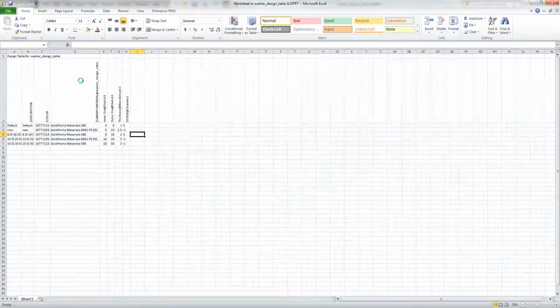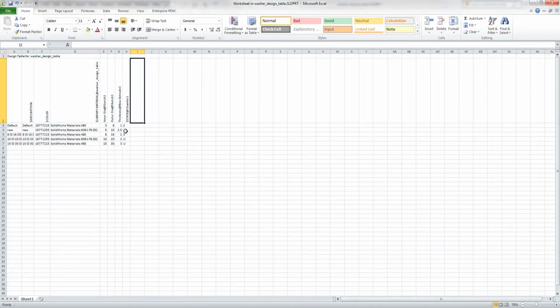One last thing I want to show you guys here, and I mentioned the drop-down lists, and you guys might have saw that pop up here. So this is the drop-down list. We can see when I click on here, it's telling me all the possible options that we can use. We can type in suppress, we can type in unsuppressed, we can use an S, U, 1, or a 0. That's going to be all the results. And then this is the actual drop-down list here where we can select those options. So each of these can possibly have an option. In this case, just that this feature does, but we could even add drop-down lists here if we wanted as well.